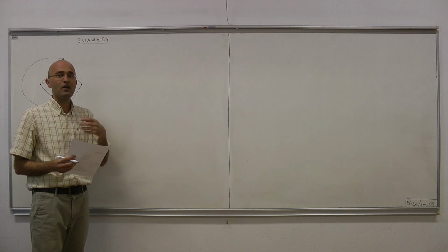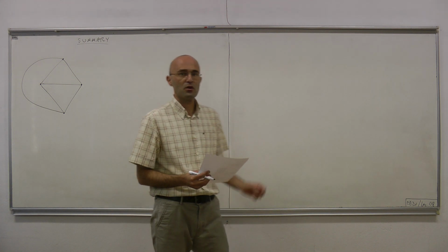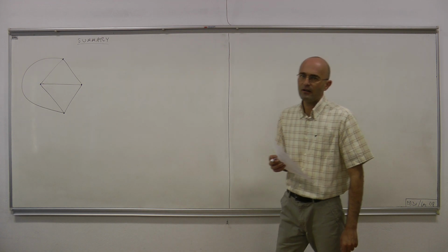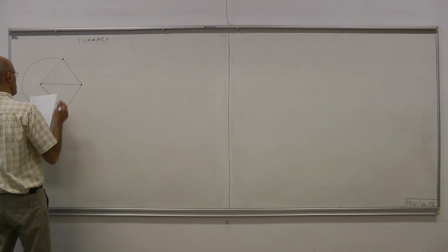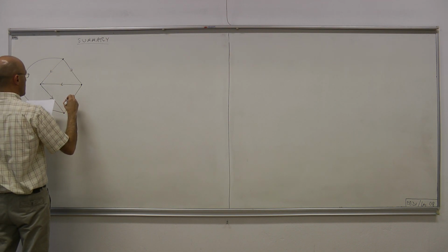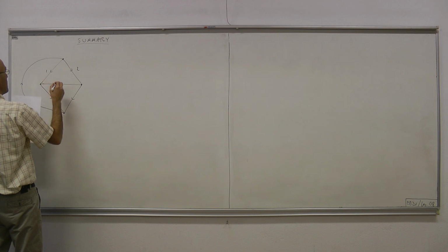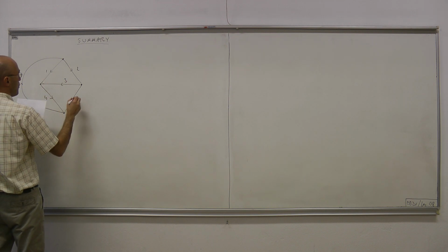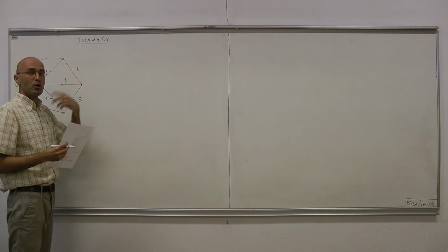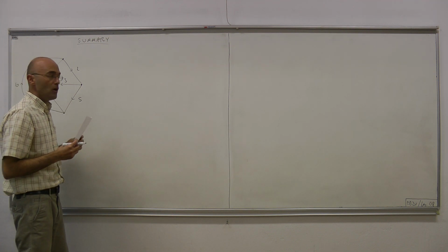So what we do is we label all the branches and all the nodes for writing KCL equations, and also we need to label the inner meshes when writing KVL equations. This was our labeling from last time. This is branch 1, branch 2, branch 3, 4, 5, and 6. We not only give them labels, but also we assign each a direction. And then we label the nodes.